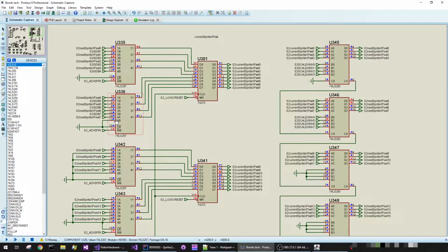But when it's actually stamping out pixels to the sprite data, it's reading the output from the add that it's doing. So what it's doing here is taking the current sprite X pixel latch value and adding in the X scale inverse value, doing a 16-bit add, and then presenting it as the next sprite X pixel value, which it latches, or selects, using this 2-to-1 selector here.